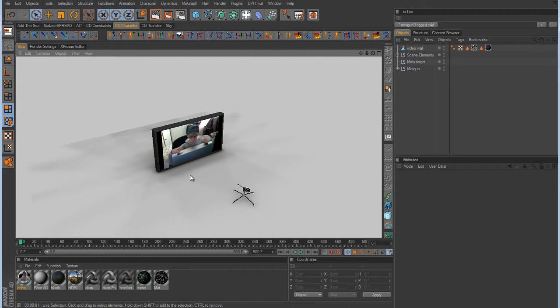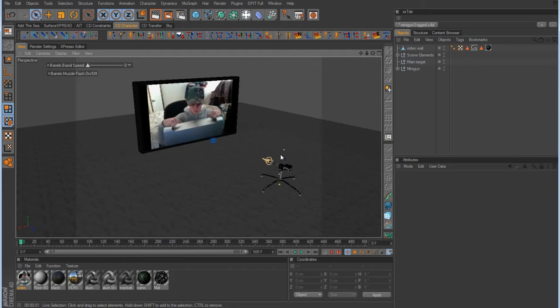And the radial pattern is being caused, of course, by the light dome. Now, right after I made the last tutorial part about the lighting, I went in here and I made a few changes. And we're going to go over those changes. Now, when it comes to the lighting, I want the light dome to be able to hit the floor. And remember in one of the first parts where we did the lighting, I made it so that the light dome was not affecting the floor, because we were getting that radial pattern of shadowing.